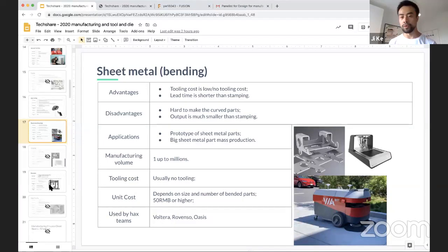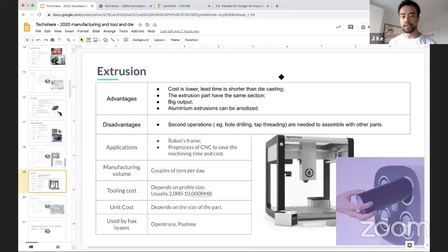And same as extrusion, right? The die for the extrusion is extremely cost effective. So the tooling for the die, if you're working with 2020s or 4040 extrusions, or your own kind of oval shape as a battery pack, the die only costs around $500. At $500, you can extrude such long, nice shapes, with very good materials and very good surface finish. It's very cost effective, right?